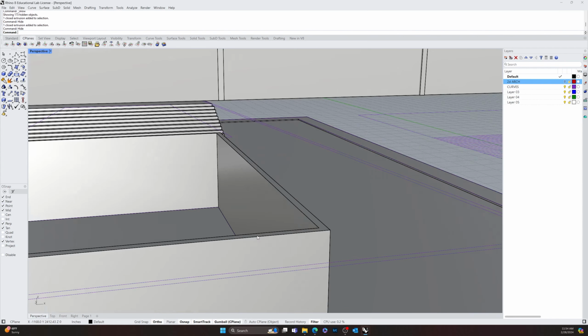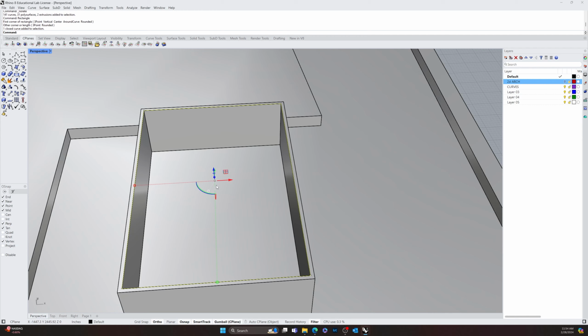I'm going to draw a rectangle inside of here. And I'm going to hold down the shift button, with the grid snap on, so that I'm doing it in increments of inches and stuff. All right, like that. And then I'm going to extrude this all the way up high, bring everything back, and Boolean difference.